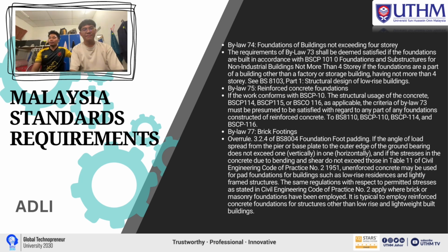Unreinforced concrete may be used for pad foundations for buildings such as low-rise residences and light structures. The same regulation with respect to permitted stresses as stated in Civil Engineering Code of Practice number 2 applies where brick and masonry foundations have been employed. It is typical to employ reinforced concrete foundations for structures other than low-rise and lightweight buildings.